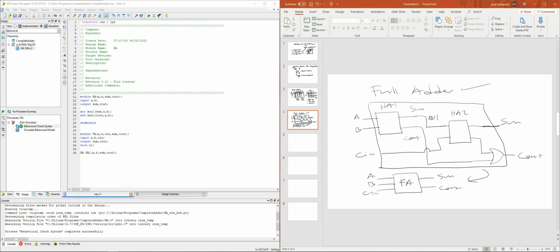Then we can see another output from half adder 1 connected as the input to this particular OR gate. This one is going to be wire 2. And this output is also connected as an input here, which is going to be W3. You can have 3 wires there. Come back here, declare W1, W2 and W3.